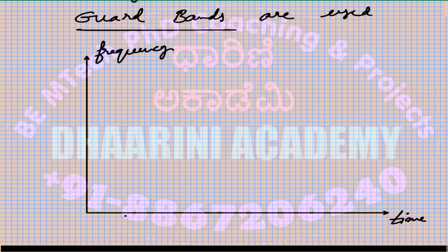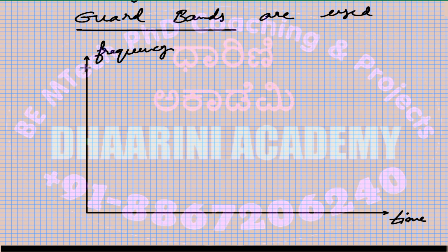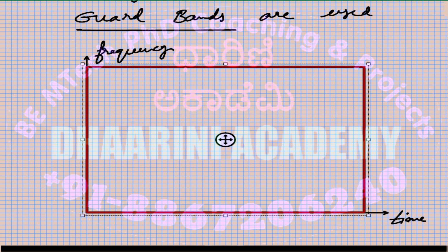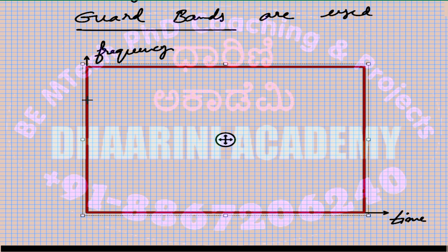So throughout the time, frequency gets divided among the users. So let's denote the frequency in this fashion. Let me assume that I have say three communication channels at a given point of time. I divide my whole available frequency into say three parts possibly, and I need to introduce the guard bands as well. Okay, so first let's divide this into three parts.